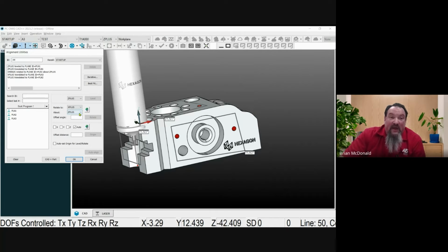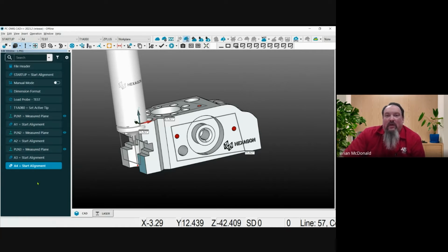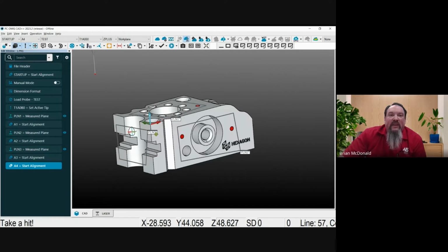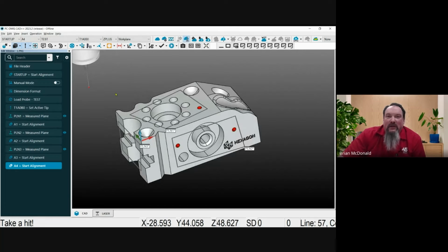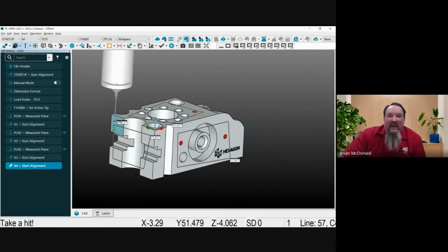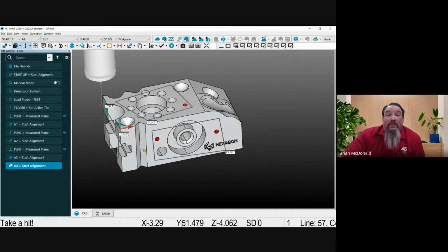Just one other thing to keep in mind while you're going through all this. Again, what are the errors of not doing a progressive alignment? How square do you have the part to the machine? If you level, then you can do a 2D feature, which would be a line. After you rotate, that's when you can start doing a point. Points are a 1D feature. If we just came in and took a point on that edge without an alignment, our approach vector and our probe comp would be off, however square we are to the machine, or however not square we are to the machine.